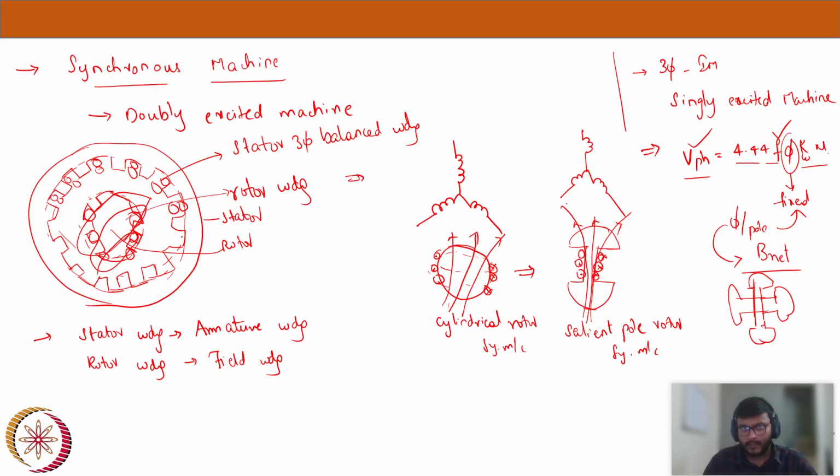Yes, when you see the light load condition, even the no load condition, the kind of magnetizing current it draws is lagging. If it is a no load, of course, it's completely lagging. It's like an inductor, 90 degrees lag you will observe. And if it is a light load condition, it will still be lagging, not exactly 90, but some angle. That's why you will always say an induction motor will always have a lagging power factor, never leading, not even unity power factor. It always supplies the lagging loads and always has a lagging power factor, but that's okay.